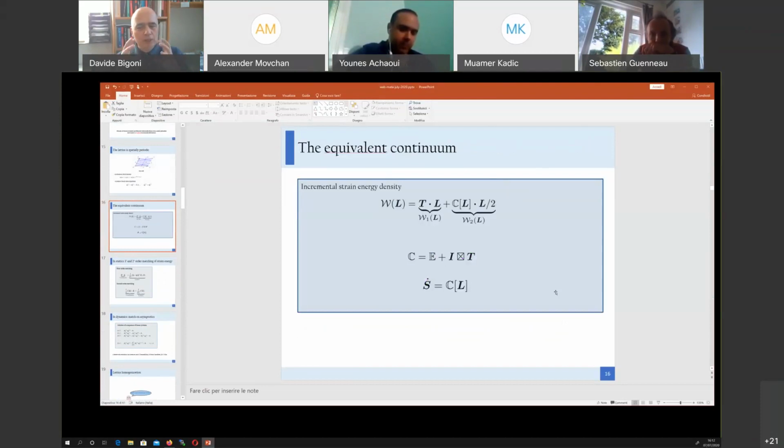We deform a nonlinear elastic material, and then the linearized response is found near a perturbation. So we have this material which has been deformed nonlinearly before, and then is incrementally perturbed. These equations relate the increment of the first Piola-Kirchhoff stress tensor to the increment of the gradient of the incremental displacement. This relation is standard, and can be found in books of nonlinear elasticity. It's still linear.